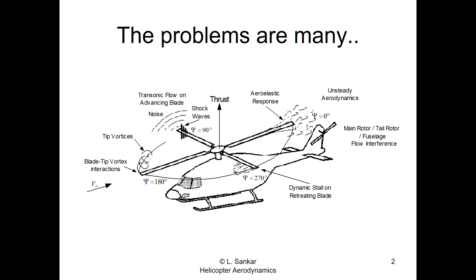When you have such a high advancing Mach number, the dynamic pressure becomes very, very high. Half rho V infinity squared gets very, very high. And also, because the local Mach number is now higher, you start getting shock waves on the surface. These shock waves can cause many bad things. From undergraduate aerodynamics, we know that shock waves can cause wave drag, increasing the drag.